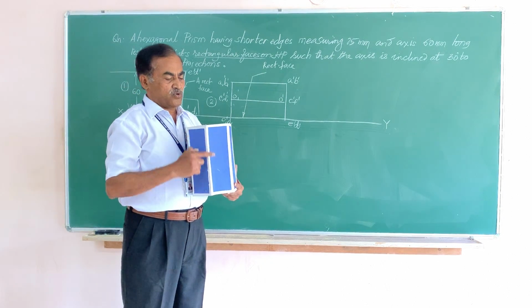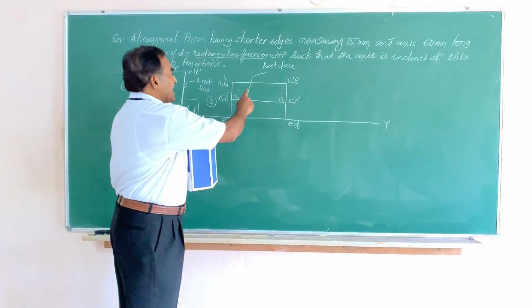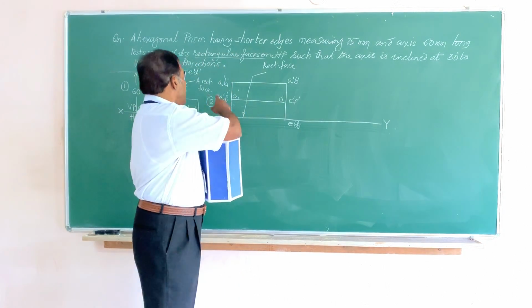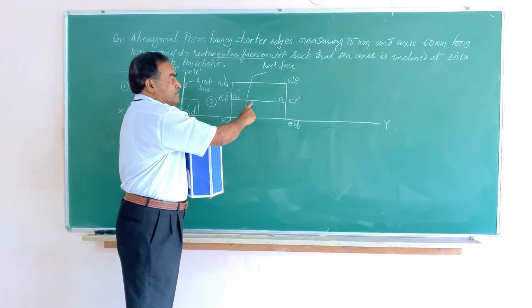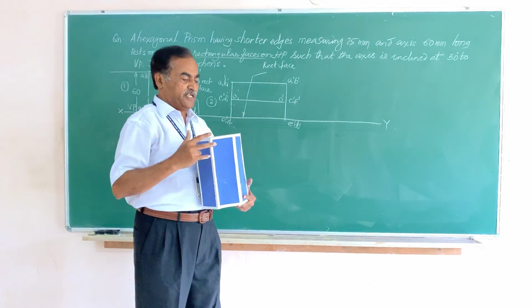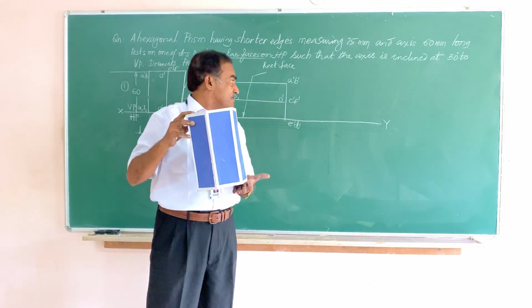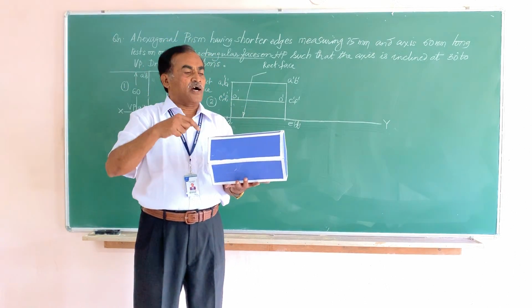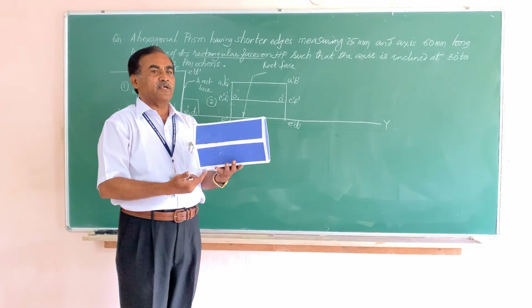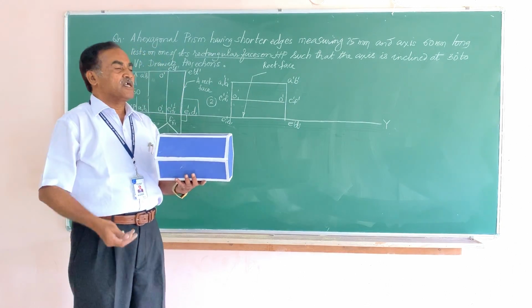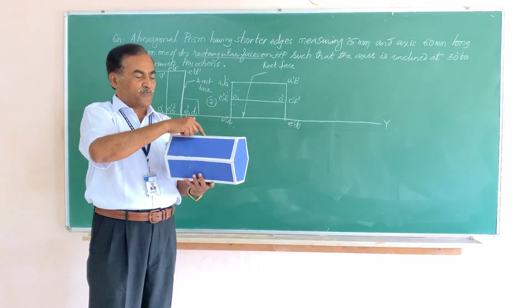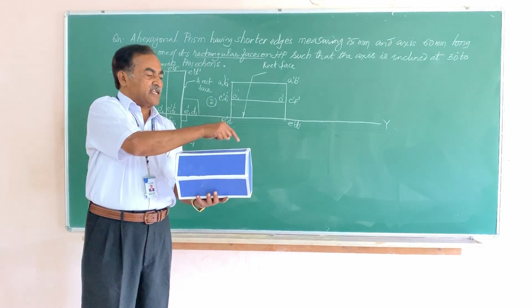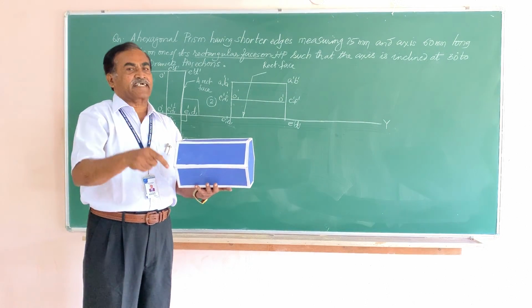You have these 3 lines, 1, 2, 3. They are these edges, the longer edges. Now the axis of the object was perpendicular here. Now it has become horizontal, that is parallel to HP. Now I am going to redraw the second figure as shown here. I am making it rest here. So after placing the object on HP on one of its rectangular faces, if you look from the top, for getting the top view, you will see a rectangle here and the short rectangle. Totally you will be able to see 3 rectangles.